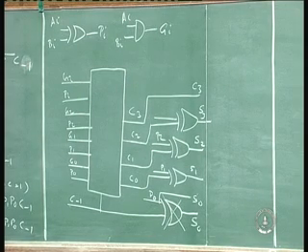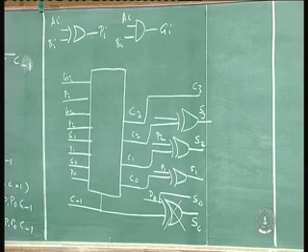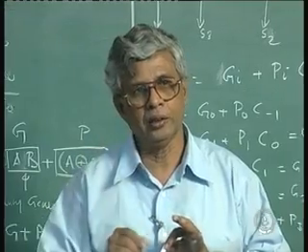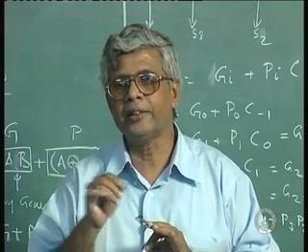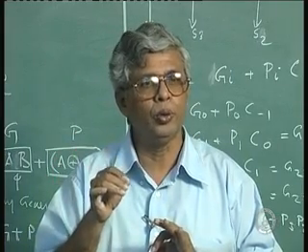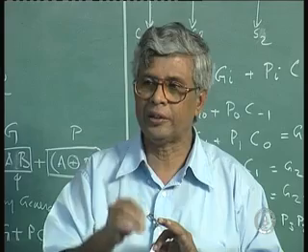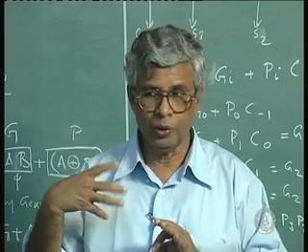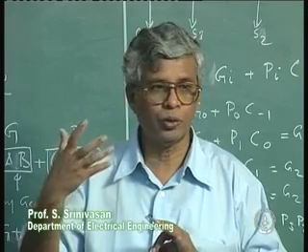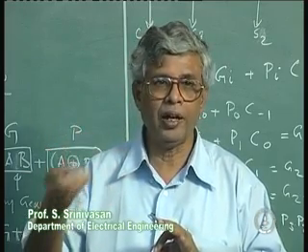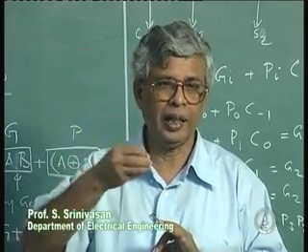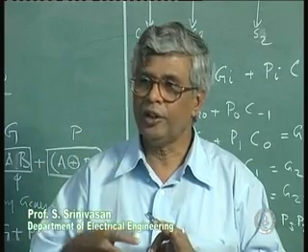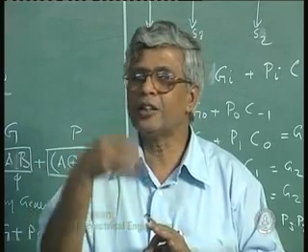As I said, I wanted to introduce a concept here. Carry lookahead adder is one of the more basic techniques to improve the speed of addition, and arithmetic is not only addition. There are lots of arithmetic operations you have to do: subtraction, multiplication, division, and for large numbers you have to make floating point, exponential numbers whose magnitude is very large. You will have a radix and exponent, that type of representation. We have to take care of all of that, but the essence is all the same.